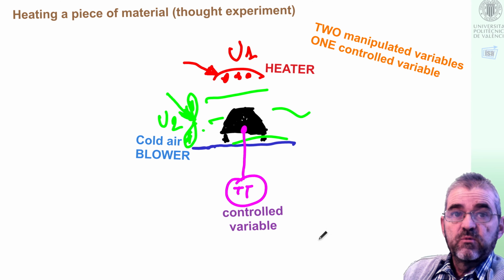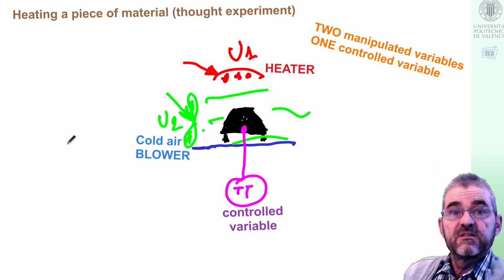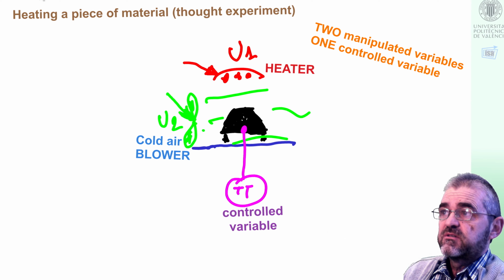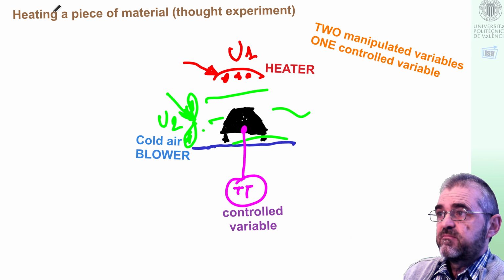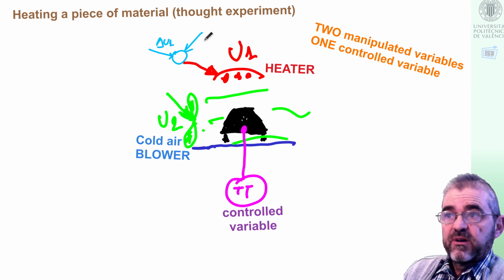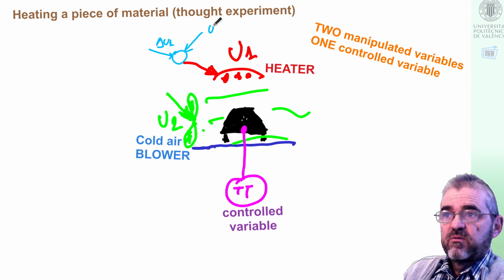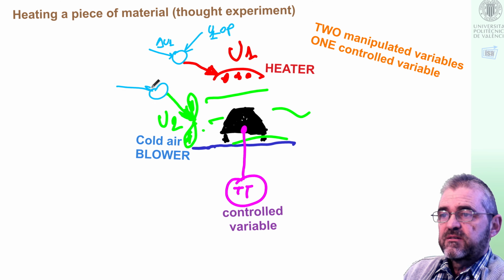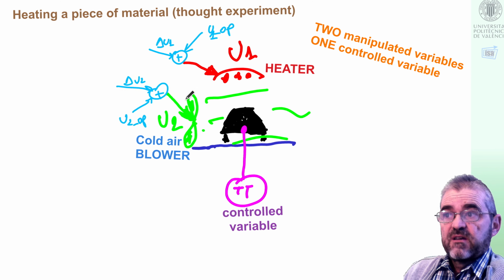We will work in, of course, linearized models, because the DC gain is the DC gain of the linearized system. Then our controller will decide the increment of U1 with respect to the U1 operating point, and likewise, we must decide upon the increment of U2 to be added to the U2 operating point.